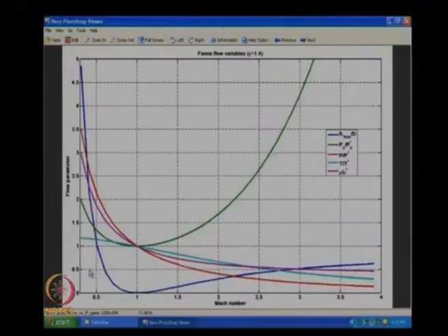Okay. Mach number was changed by so much. That also says that if, let us say, the L max was 1 meter from here, this is arbitrary units, remember that. I am not giving correct units because f and D values are not given yet. So, if we say it is 1 meter, by the time I go from here to here, let us say this is 0.65 Mach number, it would have crossed half a meter. It is changing Mach number very slowly while traveling long distances for the subsonic case. And especially when I go to very low Mach numbers, it is changing Mach number extremely slowly while it is traveling long distances.